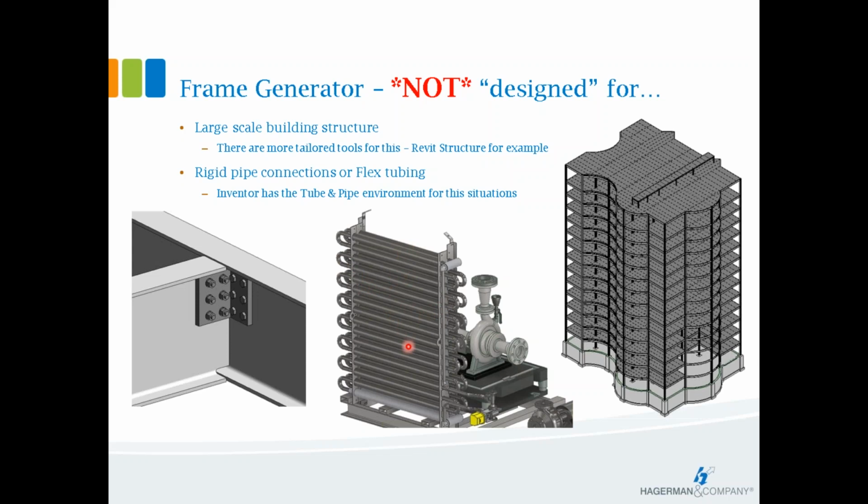The other benefit with tailor-made or specialty packages like Revit Structure for the structure on the right, Revit Structure will automatically do coping, and part of that utility, you tell it what size flange connector you want to use, what type of flange connector, if it's a T or an L bracket, how many bolts per side or how much loading, what configuration of bolts. All of that is built into the utility that's going to notch out or cope out this piece, apply the flange, apply the fasteners, and it's done. One utility, one-stop shop. That's the benefit of a tailor-made product like that.